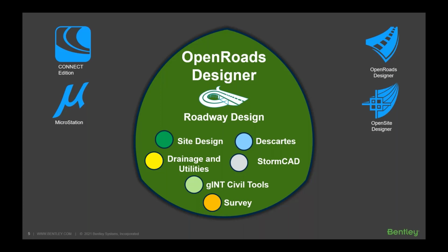It has MicroStation Connect Edition as the base CAD platform and integrates different discipline-specific workflows like reality modeling using Descartes functionalities, drainage and utilities network design, and layout. It also allows you to create storm, water, or drainage analysis because it has the StormCAD engine inside as well. It can also allow you to integrate your geotechnical data using the GEOPAK Civil tools, and of course, it has robust survey functions.